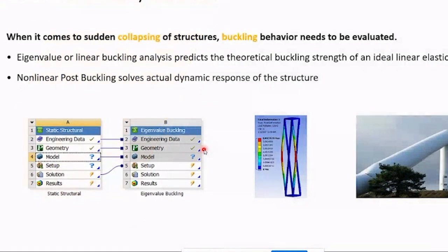Stability. In some cases, we may also need to check the stability of the structure. Stability involves checking whether the structure may undergo any buckling type of loading. Buckling is a common phenomenon in structures, especially slender bodies. Using the buckling analysis, with a similar procedure in ANSYS, you'll be able to check what the buckling safety factor is in your model.